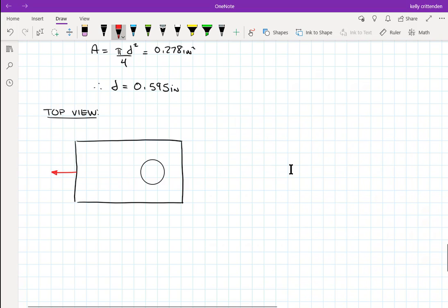But let's say we are even more aggressive with our force. Maybe we put 20,000 pounds on here. And again, we have an indestructible bolt and everything else. What could happen is it could break right here and right here, and basically this piece could come out. So we'll draw that piece out. I'll put it kind of in 3D. So this is that piece.